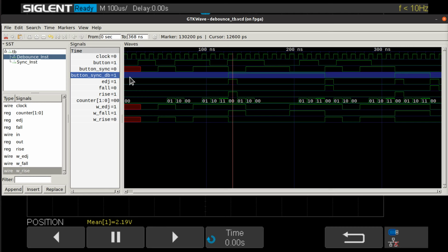Be creative, right? Slow down a clock and run that stuff in a different clock domain. Maybe it'll only need to run at 1 kilohertz. That way, one single clock tick is an entire millisecond. So the number of bits in your counters becomes much less, is my point. All right? So that's what you do for debouncers.